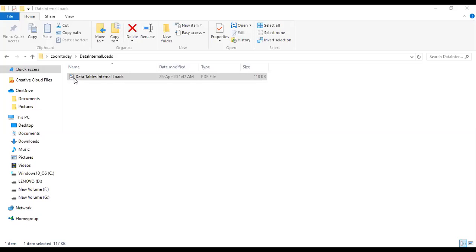An auditorium may be fully occupied, may be half occupied, may be empty, but for load calculation, you have to calculate 1 meter square per person. For example, there is a mosque. How should you know the cooling load because of occupants, because of people? In Jummah prayers, the mosque will be full, and you can assume 1 meter square per occupant. You assume that the mosque is full. All musallas are full, and knowing the covered area of the mosque in meter square, the floor area will be equal to the number of occupants, the number of namazis in there.